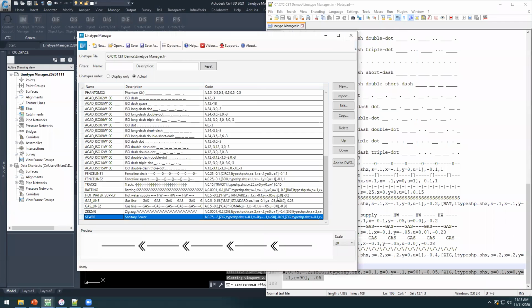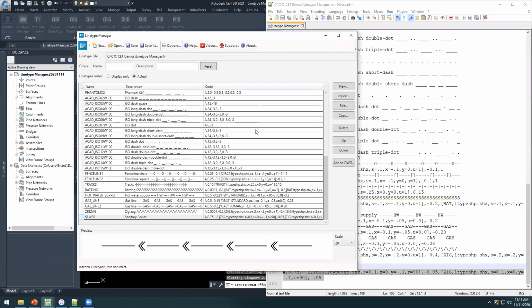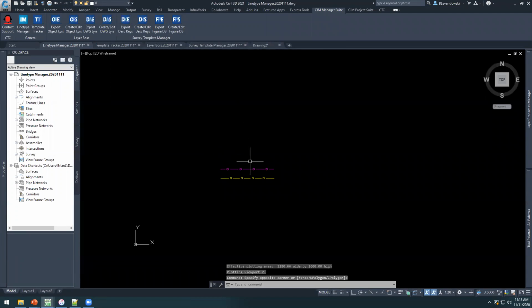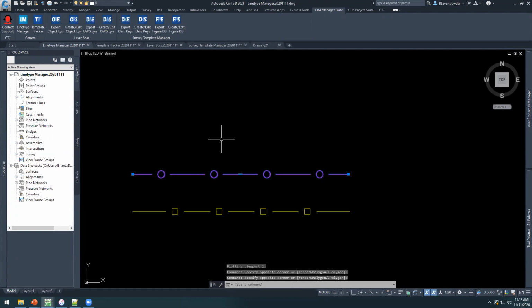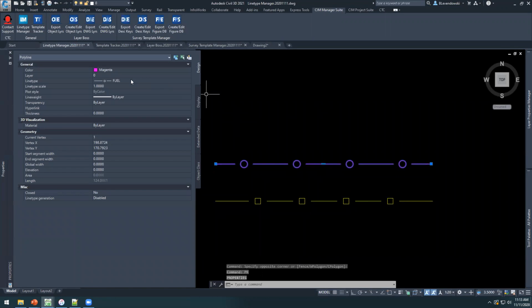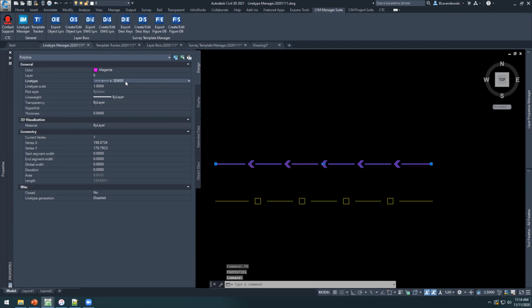Okay, Linetype Manager interfaces not just with the lin file, but the drawings as well. So I could take this sewer line type and add it to the drawing right away. Hit OK to this. Let's close out of Linetype Manager. Now if I grab an object here, or a layer, obviously we would more likely assign it in the layer, but you can see that this line type is now in the drawing. So we can easily import line types from the drawing in this way.